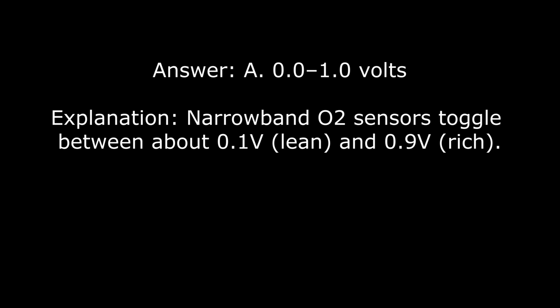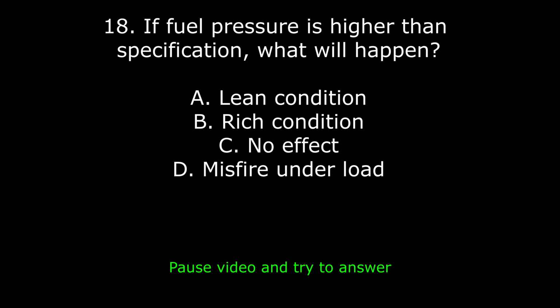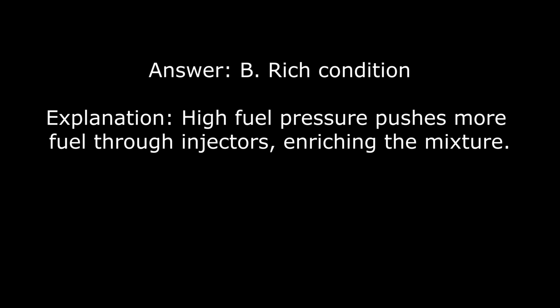rich condition. 18. If fuel pressure is higher than specification, what will happen? A. Lean condition, B. Rich condition, C. No effect, D. Misfire under load. Answer: B. Rich condition. Explanation: high fuel pressure pushes more fuel through injectors, enriching the mixture.